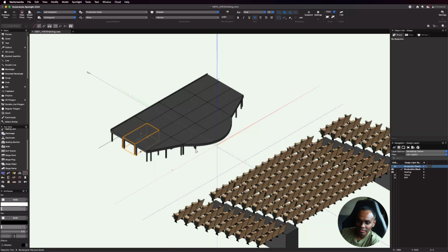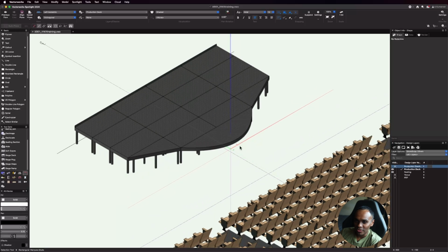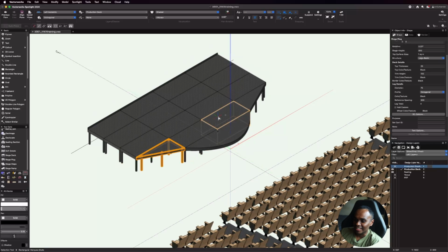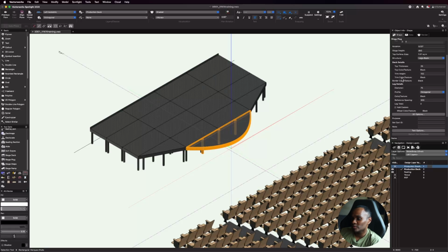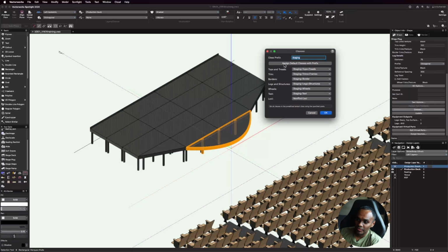You can look at it this way, but what's wrong is my front end of the stage doesn't have legs. So visually it will look a little bit awkward, but once you skin it off and mask it off, it's something that you can work around. Once you are done with the shape, remember to scroll down and once again go to classes and assign the default classes with prefix to everything.